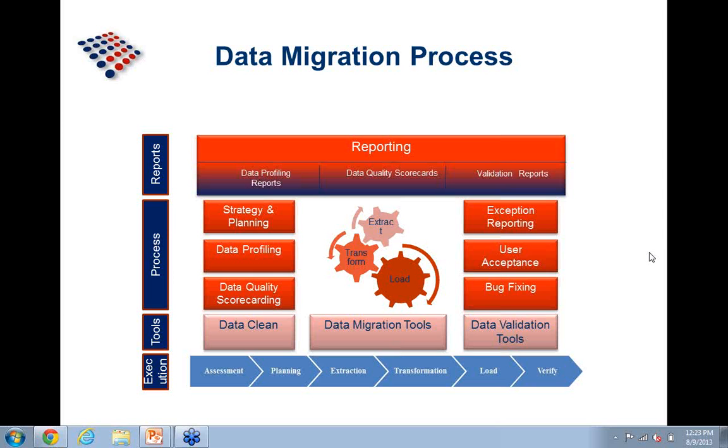The third step in the process is data extraction. Data extraction is the act of transferring the data from the legacy system and placing it into a staging system. A typical outcome in this step would be the extracted data. The fourth step in the process is typically the data mapping or transformation. Here, the data mapping procedures are performed. Data is cleansed, mapped, and transformed to meet the specification of the target Windchill system. A typical outcome of this step is cleansed data and corresponding reports.